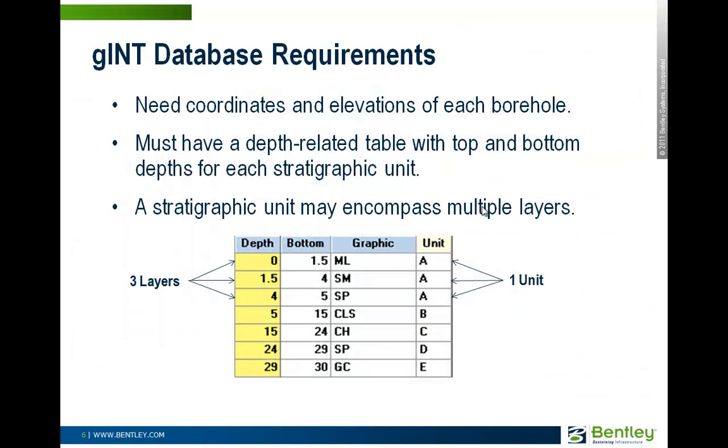On the gINT database side, you need coordinates and elevations for each borehole, and you have to have a depth-related table with top and bottom depth for each stratigraphic unit. A stratigraphic unit is generally different than your layering, which a lot of people call lithologic units. You could have multiple layers as shown here within the same unit.